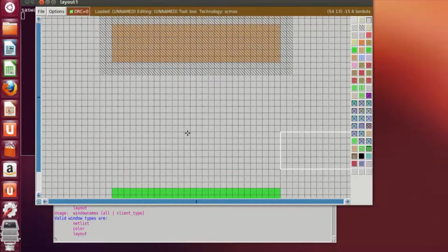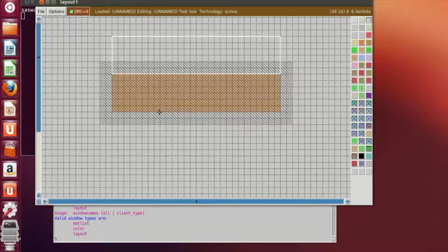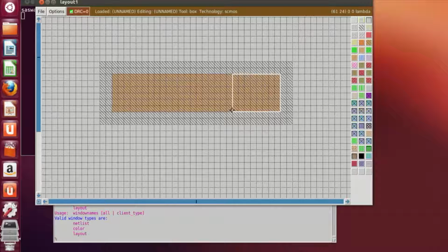Okay. Now for the convenience, let me tell you, this is the whole PMOS, right? So here to here will act as my source. This will act as my drain, and the middle will act as my gate. Source, gate and drain. So the source will be a metal layer. The drain will be connected by metal, but the gates are connected by using the polysilicon layer.